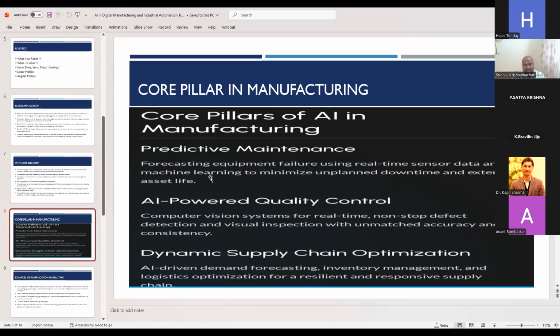So the maintenance person will come and attend, and he will recognize what kind of breakdown it is. Suppose it is a sensor failure, or a PLC output failure, or a valve failure, whatever it is, he will change it and restore the machine, and the breakdown hours will be mentioned manually.